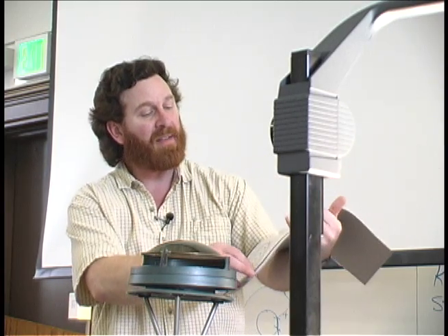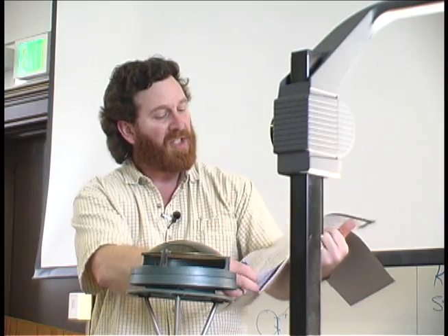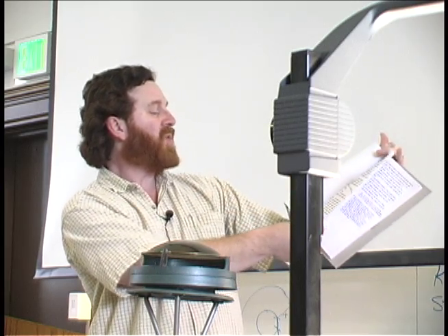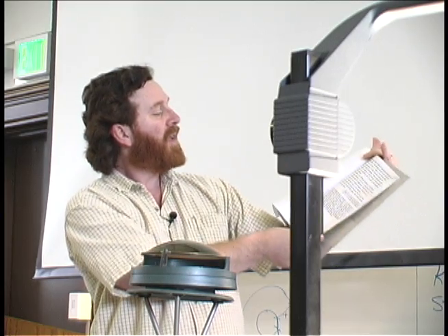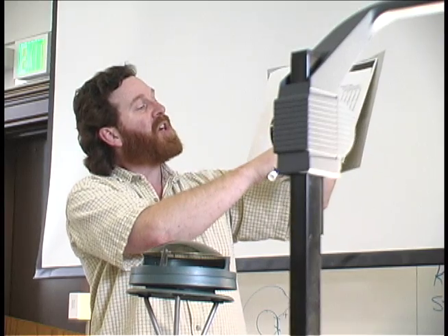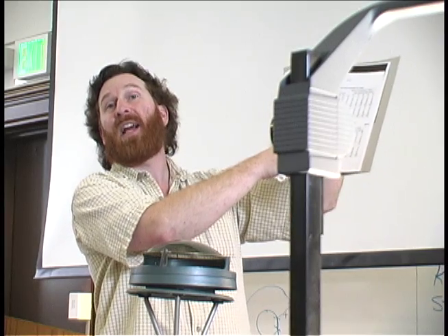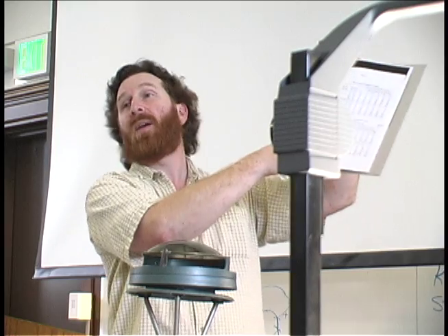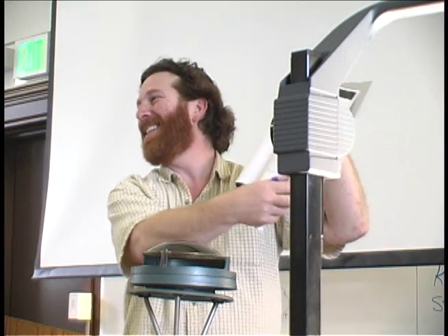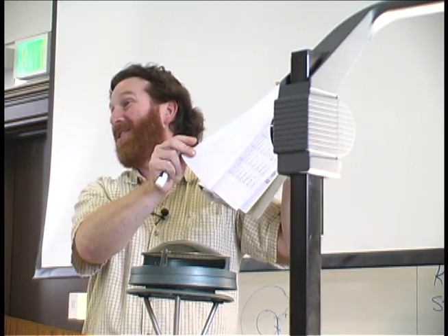There's also behind this are other charts. It talks about orientation. You can be 18 degrees east or 22 degrees west and lose less than 5%. And then right after that, this chart here shows exactly what the sun angle is for every hour of the day. So if you really want to get into it, I gave you all the information you need to be as specific and precise as you want to be.